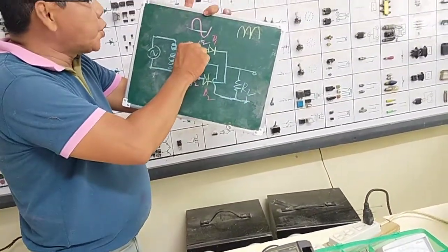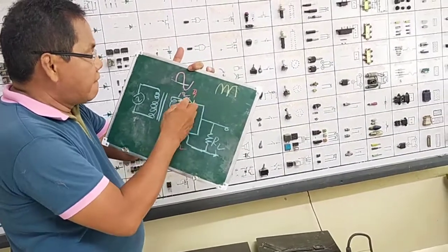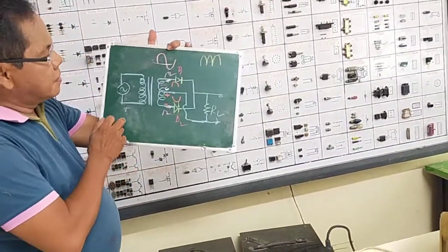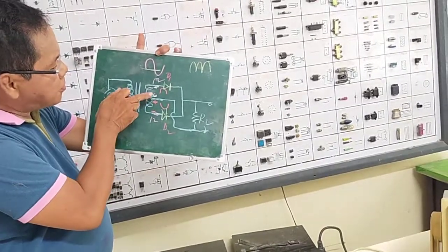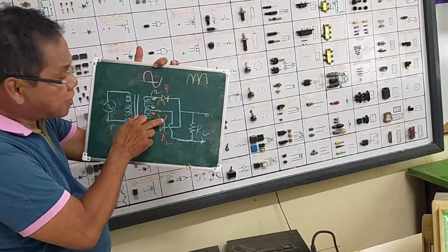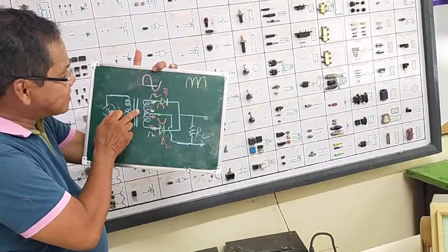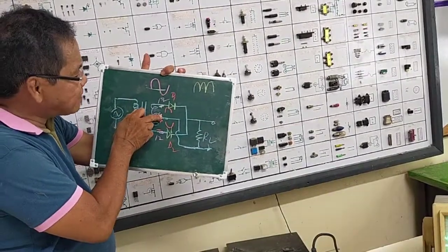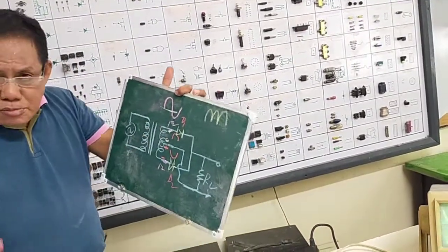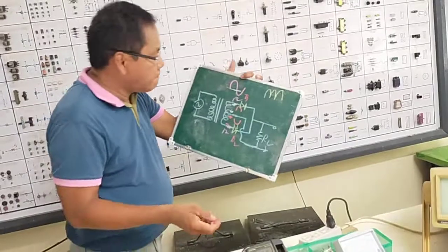These are the dual output voltage. This is like this, and the other one is like this. The output voltage of the center tap here, towards here is negative going. Whereas, the center tap here, negative to positive, is positive going. Dual output, simultaneous output voltage.